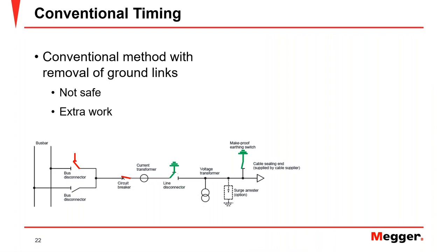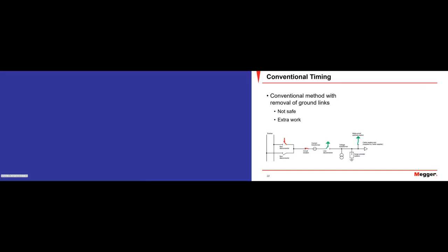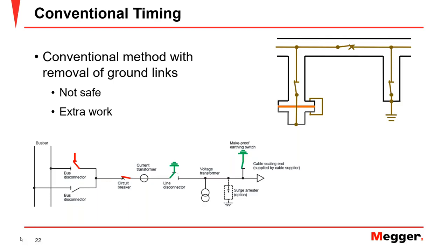Obviously, the circuit breaker is a very, very important part of our protection scheme. So we want to make sure it's in good working condition, and we're going to discuss timing measurements. As Volney pointed out, the traditional or conventional method to test entails the removal of those groundings, as that's the only access that we have to connect to the contact system of the circuit breaker.